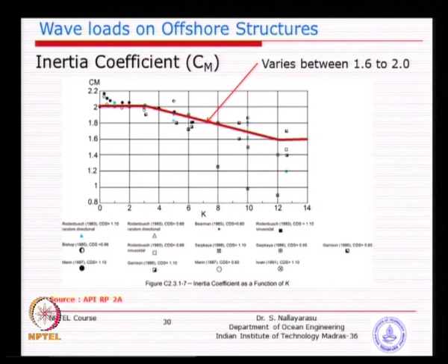If you put a circular cylinder in water and it is moving horizontally, the amount of water that moves together is almost equal to the displaced volume of the cylinder itself. So, the cylinder volume plus additional volume surrounding the cylinder. So, almost 2, that is why you see here starting with almost 2 or 2.1, 2.2 and then gradually reducing as the flow speed increases.